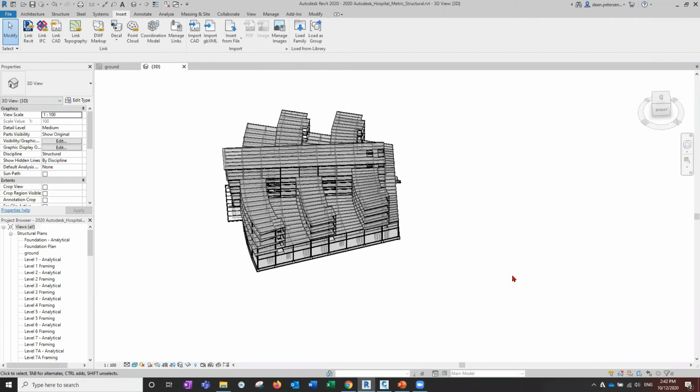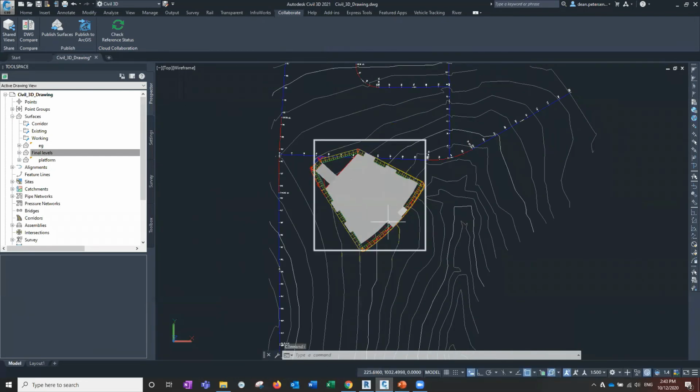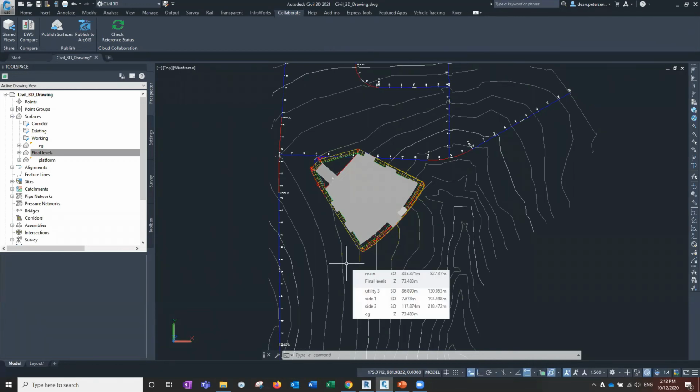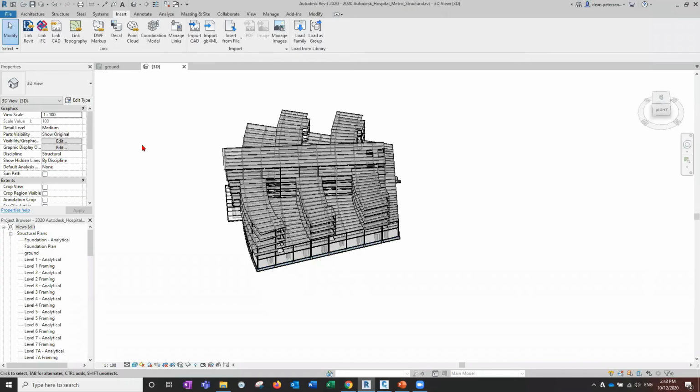And so we can then save out that NWC file again. However, you will find that the NWC back in Civil 3D here behaves essentially like it's an image. So it's not the same as a drawing where you can save over that drawing and we get the little balloon notification down the bottom corner. It doesn't do that. It's a bit like an image. So if we go and actually change it or try to overwrite it in Revit, let's go and have a look what happens.